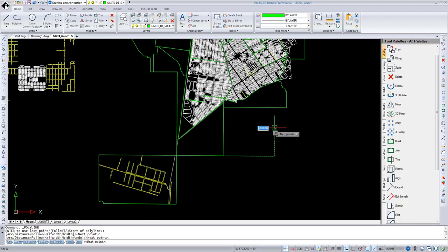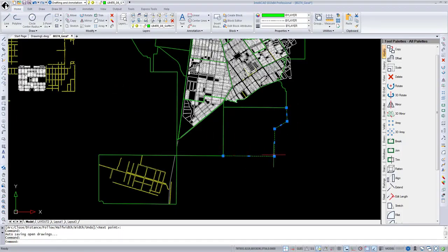Let's say I want to draw using a specific angle, so I use the tab key to navigate to the angle edit box and type 30. Switch to the previous box and see that the value 30 is locked. It's like being in polar tracking mode, but you are not limited to an angle value. Now, when I finish my command, I can select several entities and check dimensions using dynamic input. In my opinion, this feature will make your drawing life much easier.